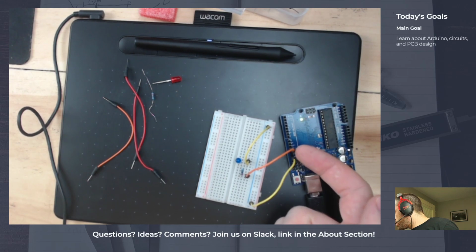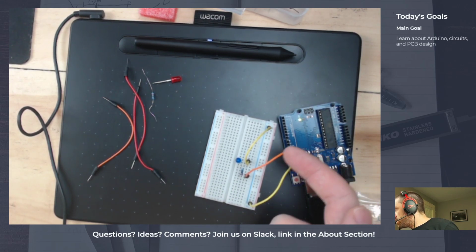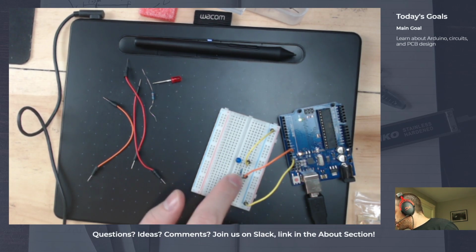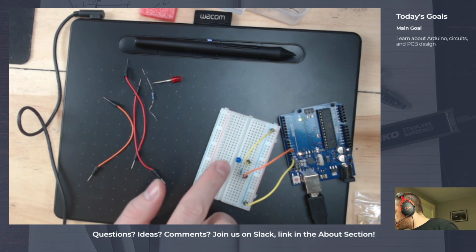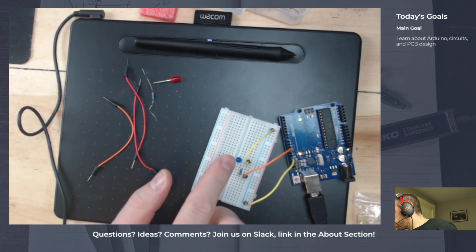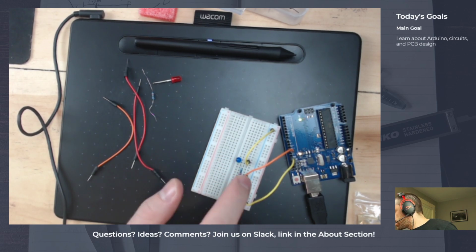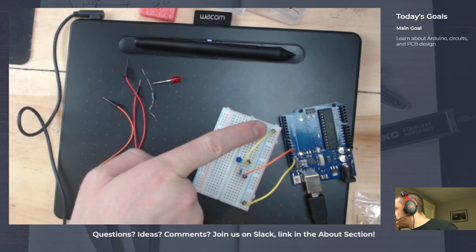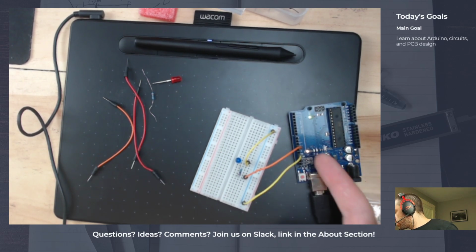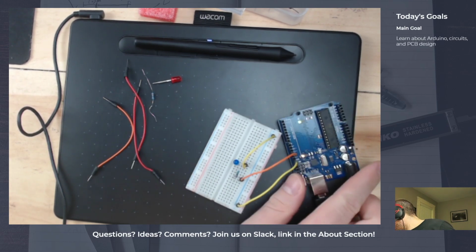So the signal, the code that we're going to write is going to turn on this pin that we have here on the orange line. It's going to go over here. It's going to connect with the resistor. It's going to go over the resistor. It's going to connect to one side of the LED. It's going to turn the LED on. Electricity is going to flow through the LED to turn it on, come out the other side, and that wire is going to go down to the negative side, travel along this rail, negative rail, and then go back to the ground on the Arduino.